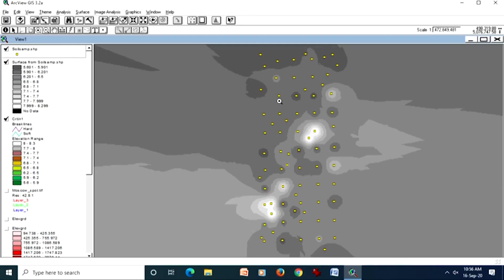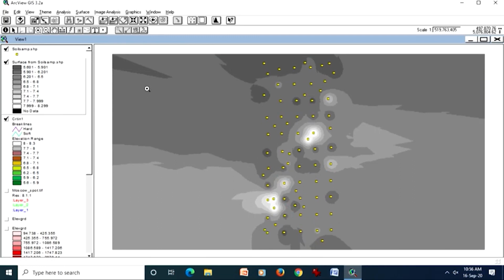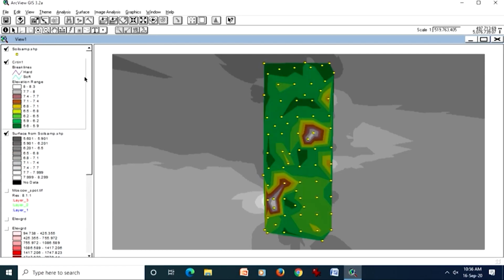But because you know that a raster can only be stored in two shapes, either rectangular or square shape. So this current one is definitely in rectangular shape. If I display now my TIN, what I am seeing is that the TIN was restricted only to wherever I had the points, and beyond the points, because in TIN there is no concept of extrapolation, not at all.